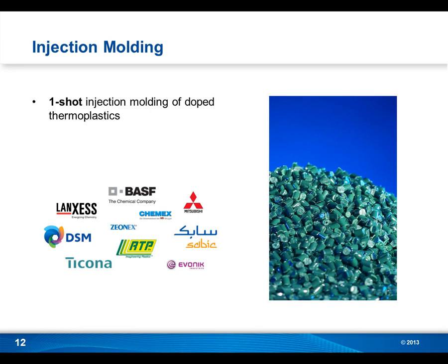Well, another thing that Stefan brought up was the large number of parts that two-shot molding required to be profitable. The other thing that it needed was a long design process where you maybe made the same part for several years. Now we all know that doesn't happen so much these days, that parts turn over very quickly. So the beauty of LDS is that you can design, have your mold built, and freeze the design way past that point.